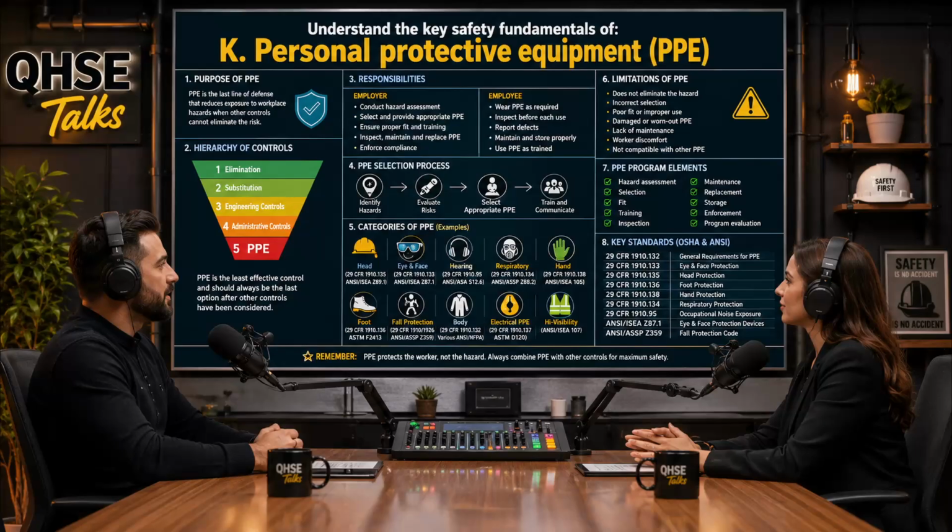How long can someone work in that? In a warm environment, a worker carrying a 30-pound SCBA while wearing heavy double gloves can easily succumb to catastrophic heat stroke within 20 to 30 minutes. To counter this, organizations often have to implement active cooling systems underneath the suit, right? Like vests packed with phase change ice packets or vortex cooling tubes connected to airlines just to keep the worker conscious long enough to turn a wrench and close a valve.